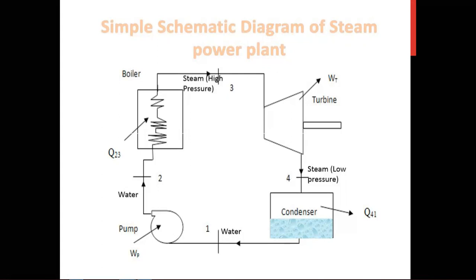Do you know what the transmission voltage is? There is some standardization, told as the national grid. In a grid, you cannot change your value. In Bangladesh, the frequency is 50 hertz, or even in Asia, the frequency is 50 hertz. That is standard. You cannot change it. In the USA, the frequency is 60 hertz. In Bangladesh, there are some standard transmission voltages: one is 230 kilovolt, one is 132 kilovolt, another one is 400 kilovolt. It cannot be changed. You have to take one of three.